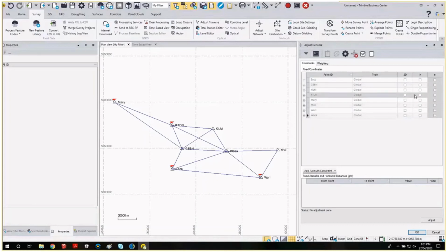When we do get to the point of locking these, we shouldn't ever lock a combination of ellipsoid heights and elevations or orthometric heights, because it creates a poor least squares adjustment constraint, where we should either constrain one or the other and just stick to it really. So if you're dealing with AHD derived heights and spirit leveling, as well as the GNSS two-dimensional positions, then pick out which ones you're going to do. Don't do a combination of the two.